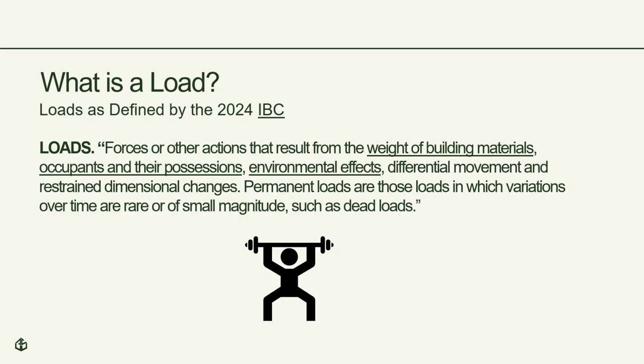Now let's start getting into loads. What is a load? The IBC defines what loads are, and when designing the wall bracing system, we'll be particularly focused on the loads that are the forces that result from the weight of the building materials, the occupants, their possessions, and environmental effects.